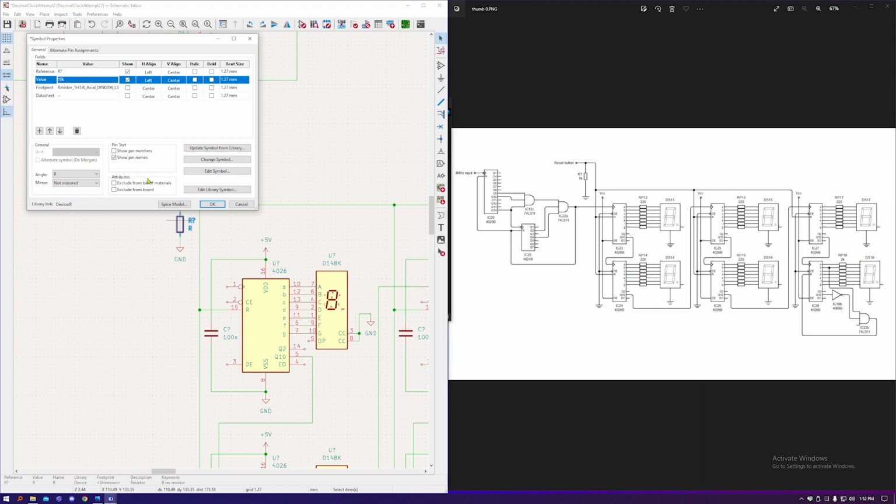So actually you can see it mentioned here, bill of materials. If you've got a circuit with 1,000 resistors on it, if you've got 100 different values and 10 of each, that's going to cost a lot more to buy than 1,000 of one value, which realistically you're not going to be able to achieve. But for example, if you had 47k, 100k and 220k on the board, just have a think about, can you make them all into 100k? Will it actually affect the circuit?